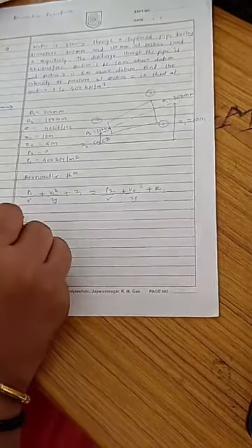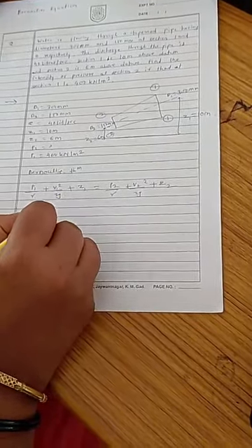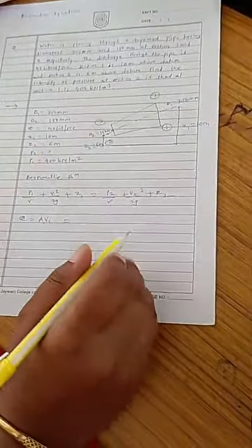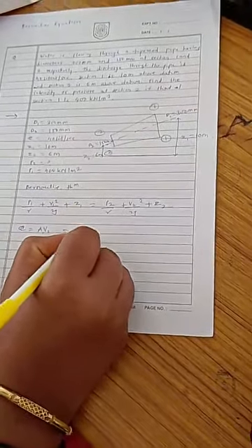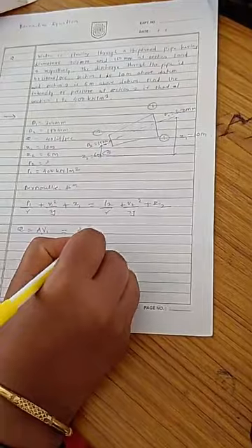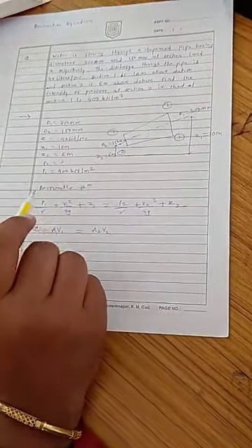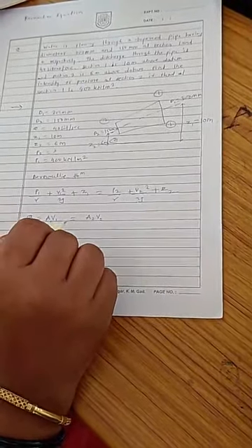So what is that continuity equation? Continuity equation is nothing but discharge equal to A1 V1, meaning the discharge throughout the section will be the same. So discharge is Q, and velocities V1, V2 and areas A1, A2 are going to change, but the total discharge will be the same throughout the section. So Q equal to A1 V1, Q equal to A2 V2, that we can put.